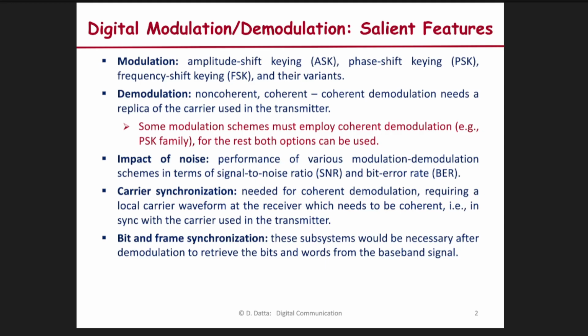Another thing is that when you want to transmit through radio transmission, then the size of the dipole antenna, or any antenna, will be proportional to lambda. For a dipole, it should typically be lambda by 2, as I have shown here. Now, lambda is inversely proportional to f, that is, c by f.